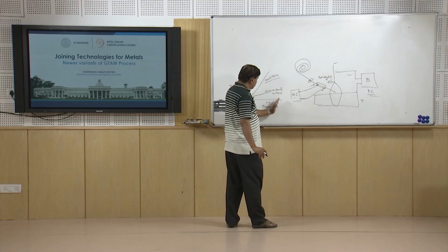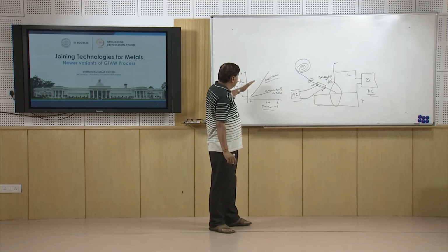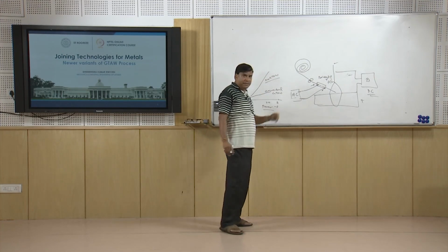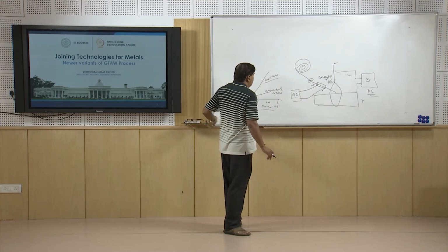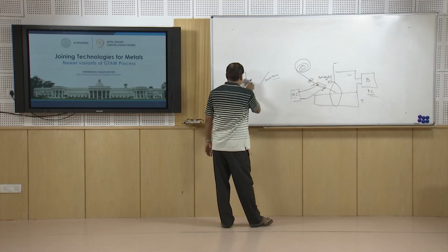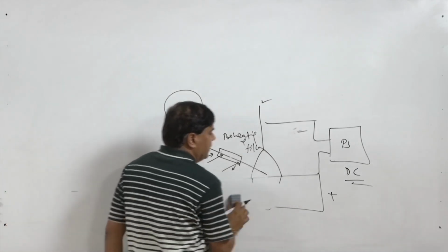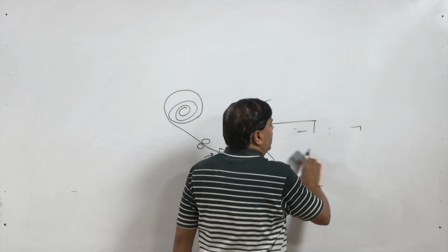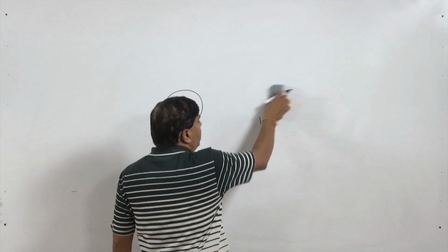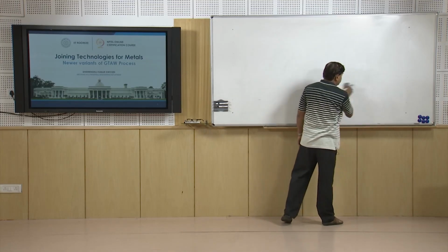So, increasing the power of arc increases the deposition rate in case of the hot wire GTAW process at a very high rate as compared to the conventional GTAW process. This is how this process helps to overcome the low deposition rate related issue of the conventional GTAW process. This is particularly useful when working with thick plates and quality weld joints are required. So, the use of the hot wire GTAW will help in developing quality weld joints while achieving a high deposition rate.